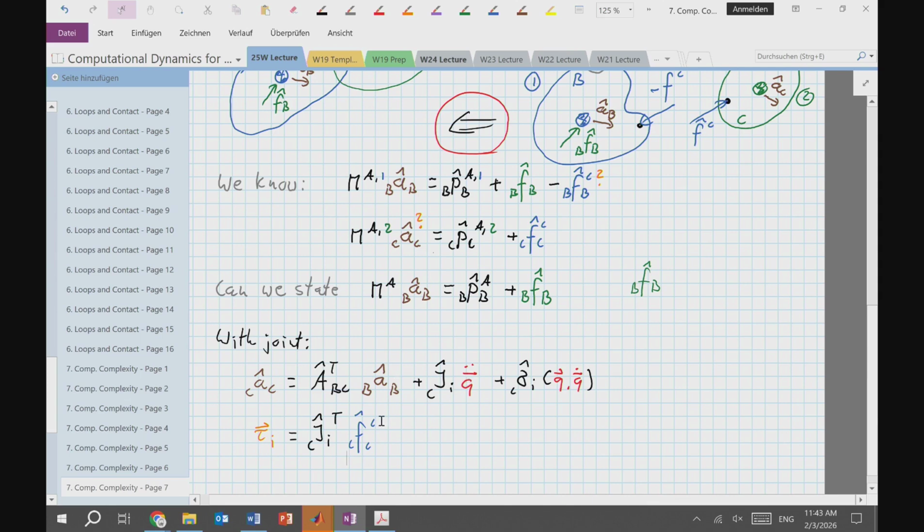So overall, what this will give me here is an additional 6 equations, or it will reduce the number of unknowns by 6, where I started by saying there's 6 I don't know here and 6 I don't know here, where the reality is I have nq quantities that I don't know here, or I should say n, because it's just the number of motion primitives in this joint, n quantities that I don't know here, but I have n bits of information about the joint forces. So just as a counting argument, this should check out. Let's see where this goes.